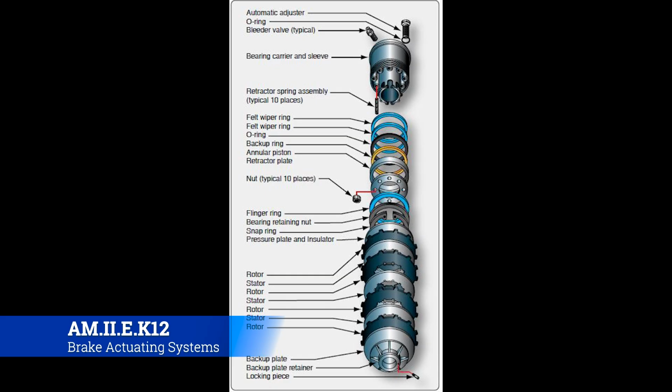And so since they're very, very heavy, they need multiple discs, just like we saw, an additional disc being added on. This category of aircraft is going to need multiple discs to get that friction to where we need it to be in order to stop on the runways they go into. Now, you wouldn't think that much about these, but these are the type of things that limit what aircraft can go into what airport.